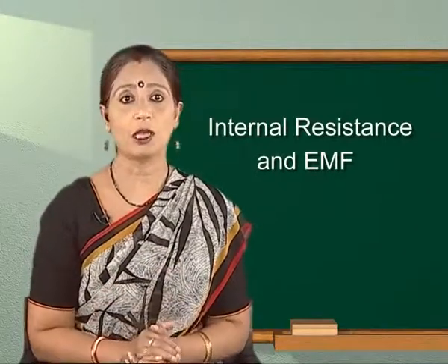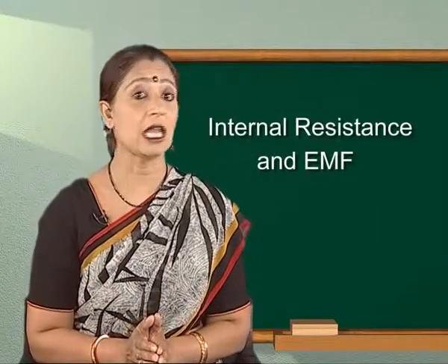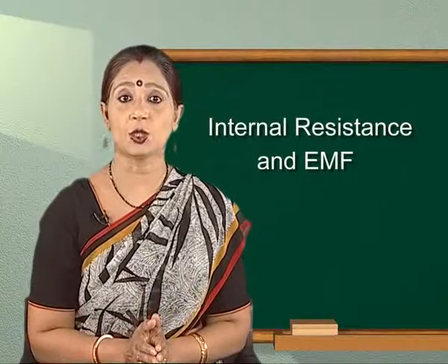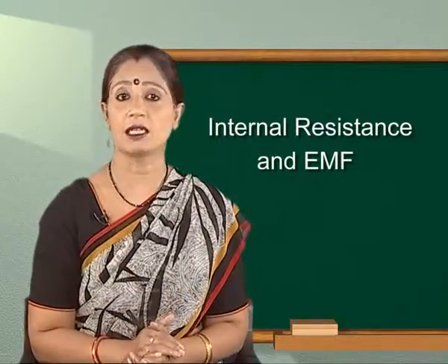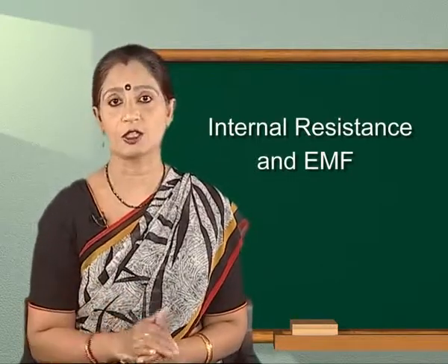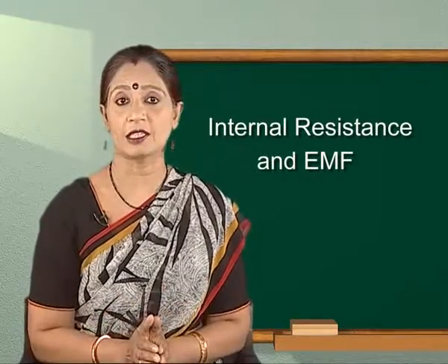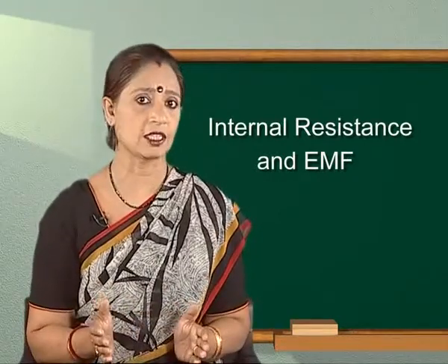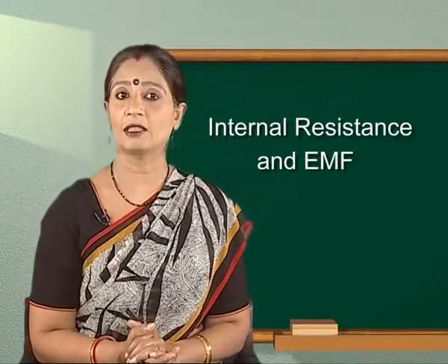It is also important to know the internal resistance of a cell cannot be measured using the resistance or ohms setting on a conventional multimeter, since it requires a current to be observed. However, it can be calculated from current and voltage data measured from a test circuit containing the battery and a load resistor.